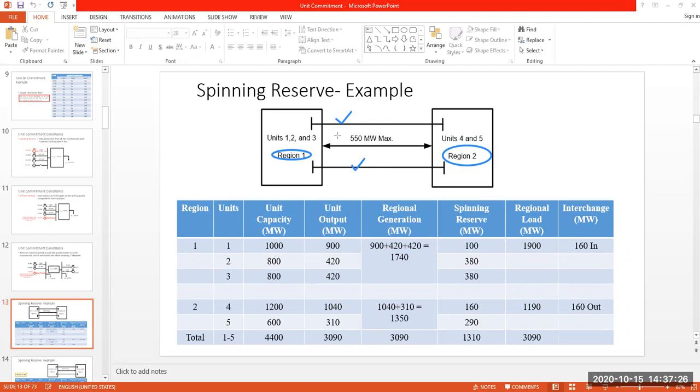And in between, we have included some numerical values to represent the limits on the power flow over the interconnection, okay? So that means these transmission networks, which connect region 1 and region 2, have some maximum capacity that they can allow. If the flow is beyond that, you are going to overheat your network or interconnection, and ultimately the network will melt down due to overheating, okay?